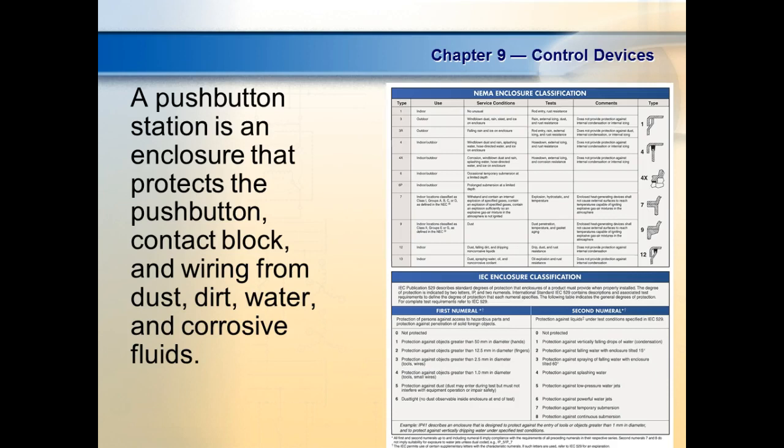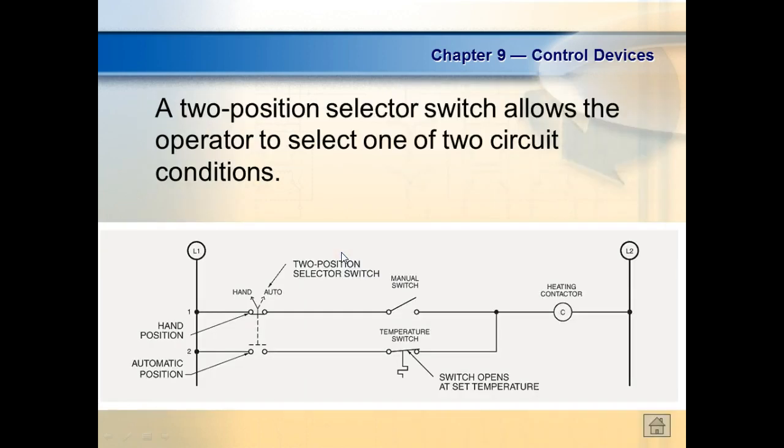So what we do on a selector switch is this is a two position selector switch. One could be forward, one could be reverse, one side could be open, one side could be left, one side could be right, or just ours is labeled auto and manual. But what it shows us is it gives us a solid line going to the left, and then it gives a dash line going to the right. Does that make sense?